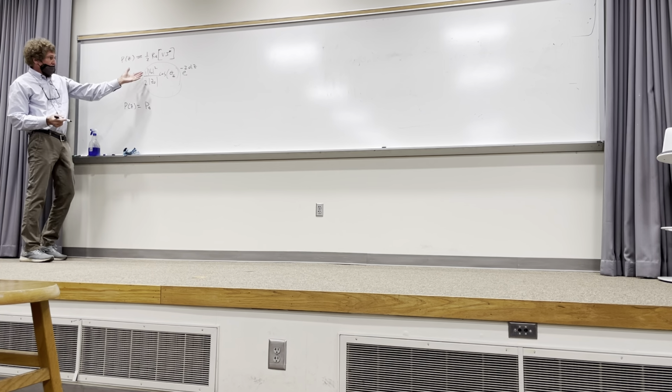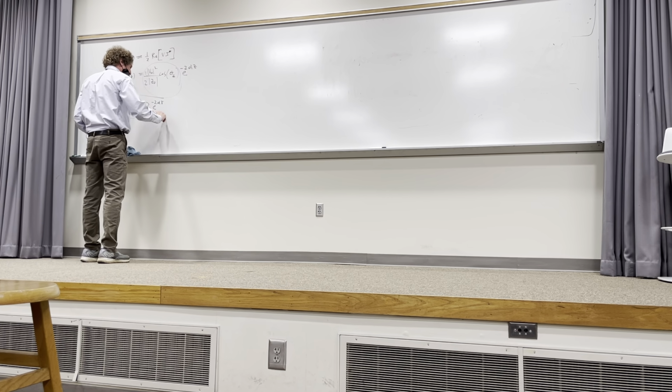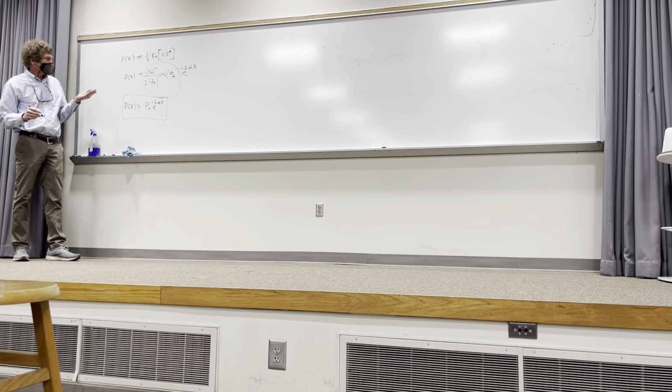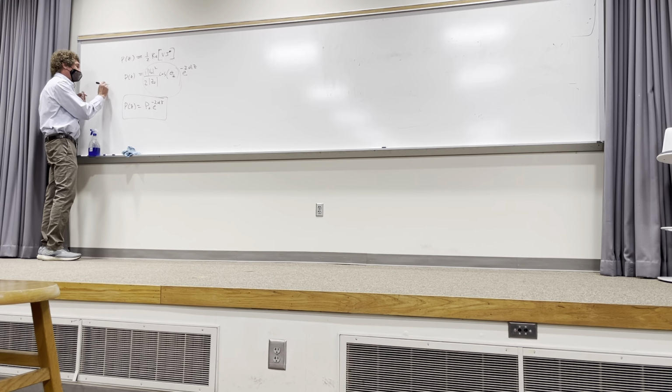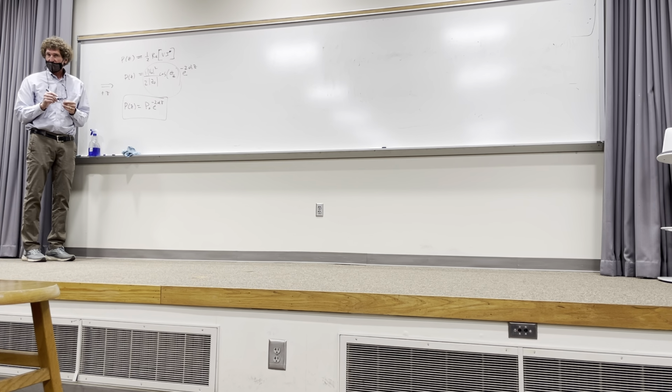Whatever it amounts to is P0, e to the minus 2 alpha z. And this is the power that would flow down the line. Now there are some natural questions, like where do you get V naught from. These will be answered shortly, but I'm just telling you this will be the form it takes. And it is for a wave traveling in the plus z direction. So we're ignoring any wave in the minus z direction at this point, to get down to the interesting points about it.